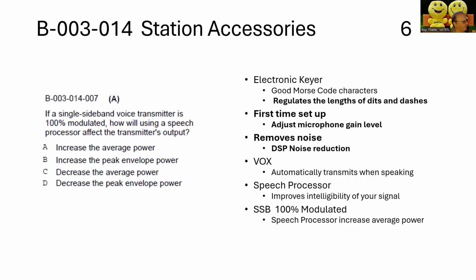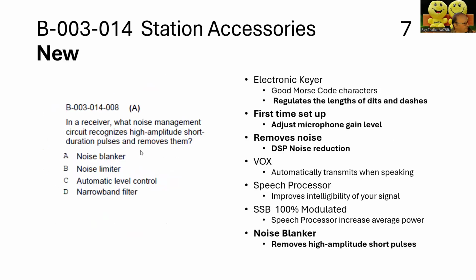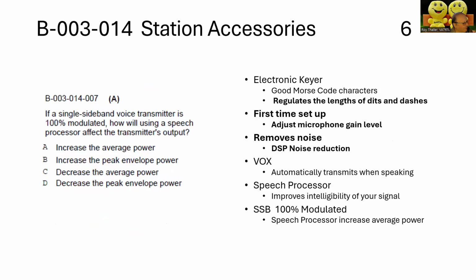In a single sideband voice transmitter is 100% modulated. How will using the speech processor affect the output? So with the speech processor, it will increase the average power going out. However, if you have too much speech processor, you do not get more power. You just distort your signal.